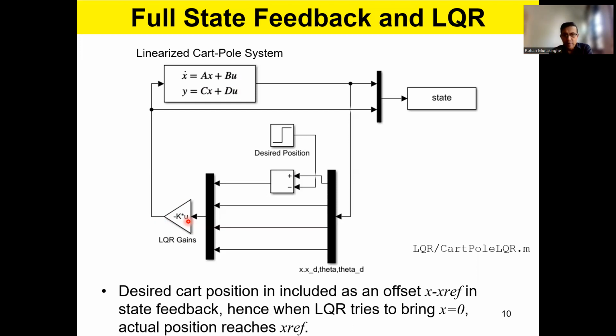So you have the state feedback multiplied with the gain, and that's the control signal. That was the policy, right? If you refer to the state feedback control notes, you can see the control policy U is equal to minus Kx. You can see it over here, minus Kx. Sorry about this U, it should be X, okay?